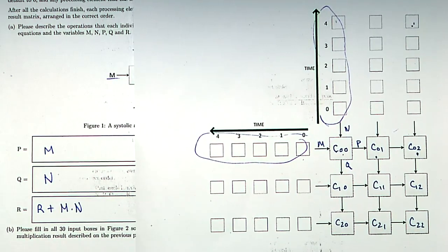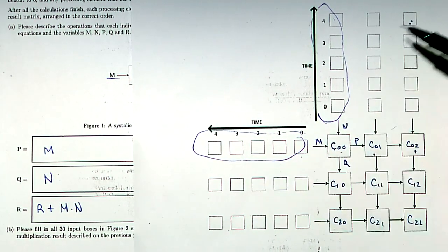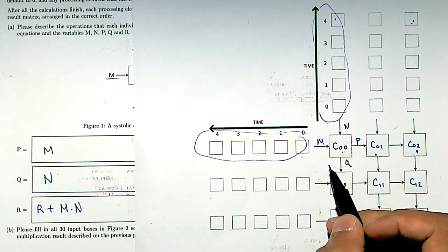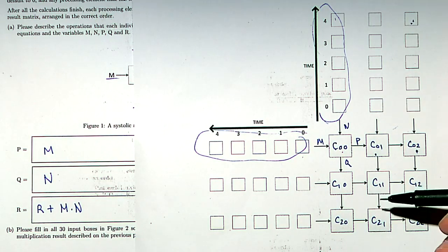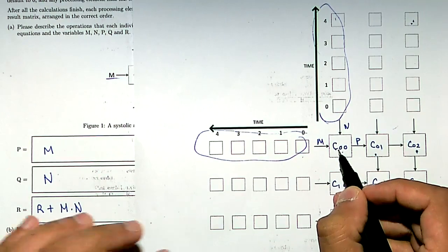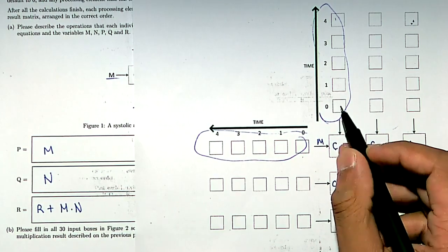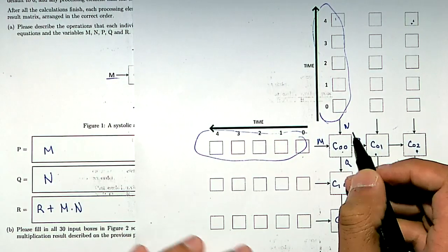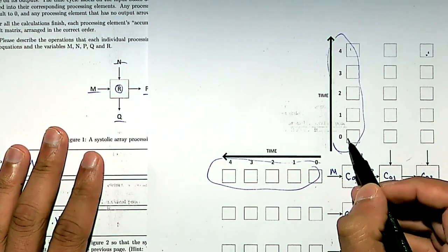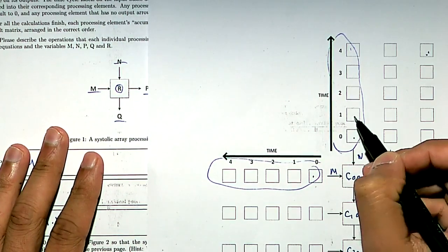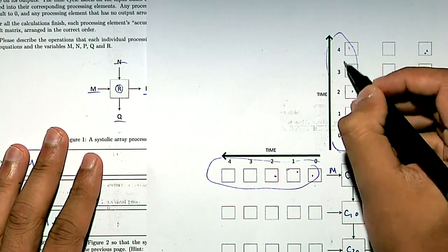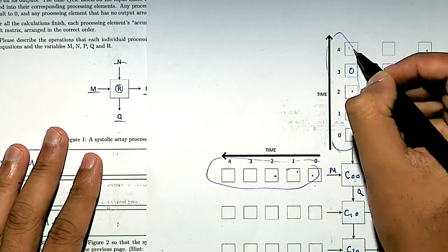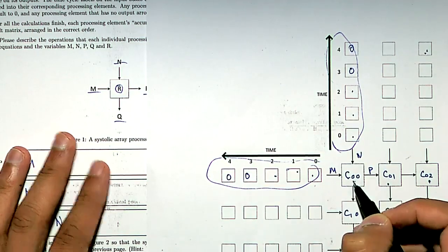And so the last part of this question is to figure out how to organize the data such that we get this computation performed correctly. So we can think about this in terms of at what cycle the inputs will reach particular elements. For this first element, in the very first cycle, we'll have data to compute with. So we want to put the first elements we can here. And so we can put elements here and here, and the cycle after, and the cycle after. And since there's only 3 we want to do, we can just leave nothing in the outer 2 cycles, right? So we can just have 0 inputs here, because we don't need to do anything.